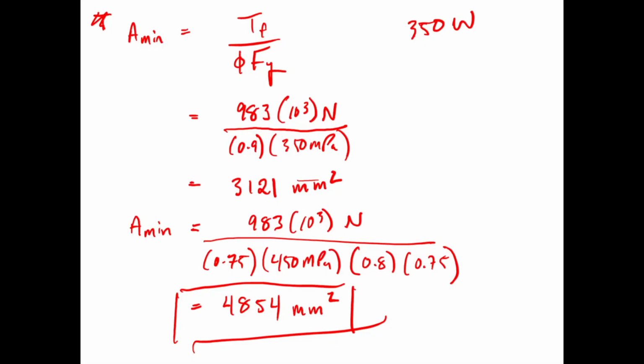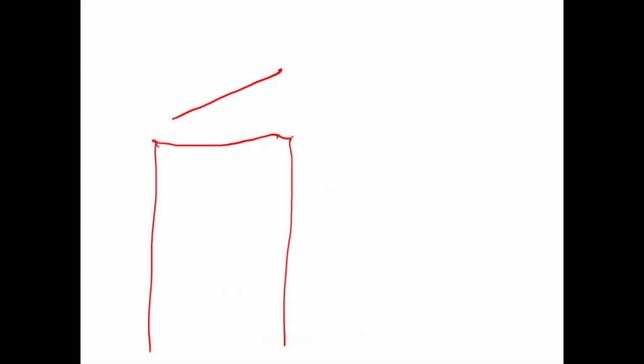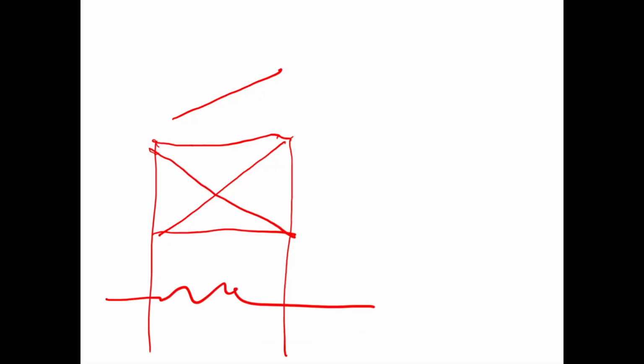Okay. So we're going to basically say on our sketch, or maybe I'll draw this. So here's our brace frame, and I'll just make a break line here. So we're going to specify basically C250 by 37. Our factored tension force is 983. I'm probably just going to write this as TF is 990. Okay, and as long as they know that it's tension-only bracing, they're going to know they're not designing it for compression. So TF, the factored tension force that we're designing for, is 990.